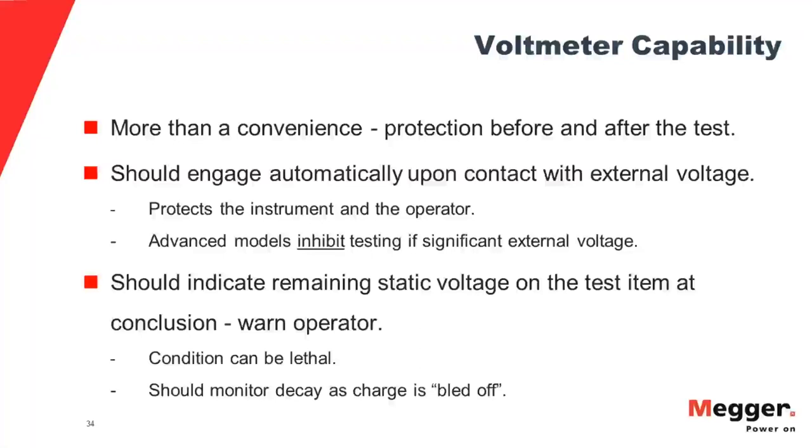That will charge up, and that will be stored at the end of the test. The operator goes up and tries to disconnect the leads and accidentally gets across the voltage. That can be lethal. A good quality modern tester will automatically begin a discharge circuit and tell the operator that that's happening. So all you have to do is look at the display, and it will tell you what is going on.